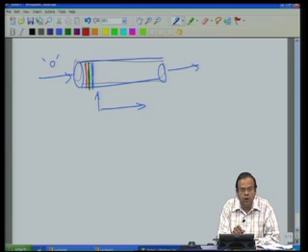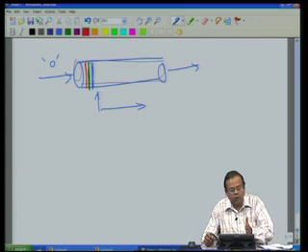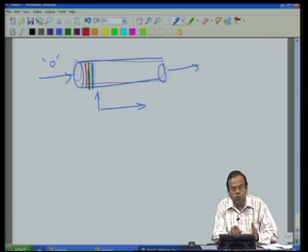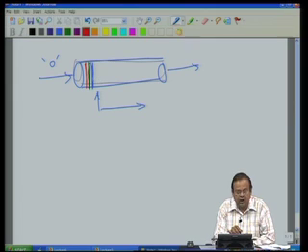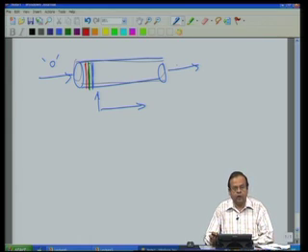So, for example, in this pictorial cartoon, these blue and green fluids do not mix with each other, they continuously move from this particular end to the exit of the reactor. So, that is to say that there is no axial mixing. So, the concentrations or fluid properties or reacting mixture properties, be it temperature or any other property, is continuously changing as we are moving along the direction of the flow. And this is what is an ideal plug flow reactor.